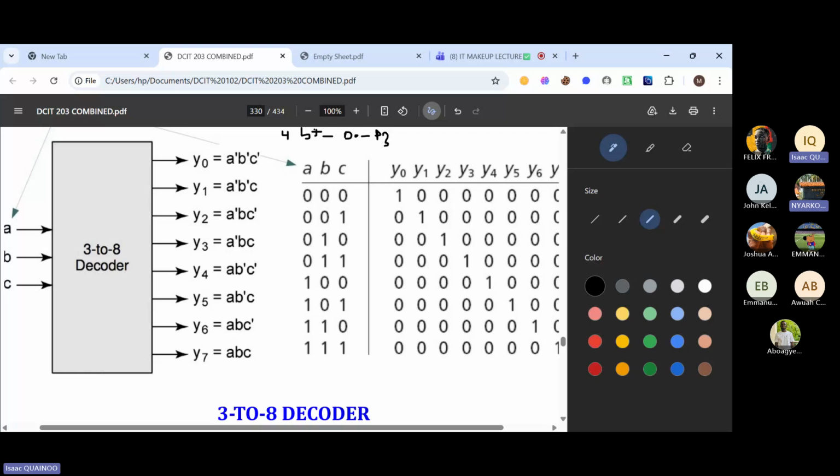Yeah, I got the question right. Okay, so I think we are yet to get to priority decoders, but when you take priority decoders, basically it gives priority to the highest input. So if, as said, D0 to D3, D3 takes the highest priority, and they are usually used in things like, for instance, lift systems, where people can press two inputs.